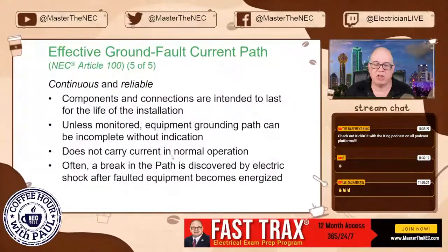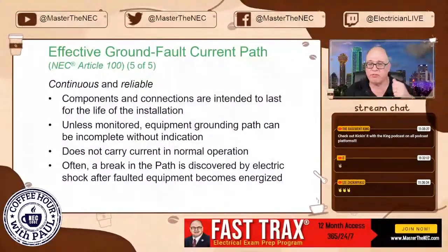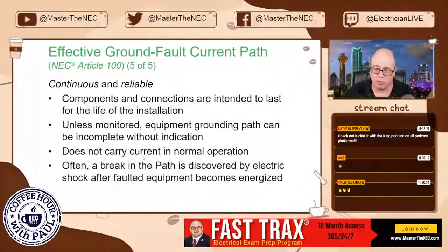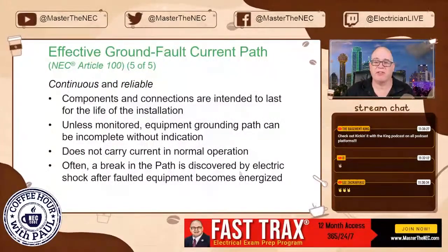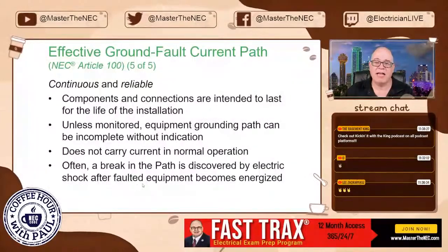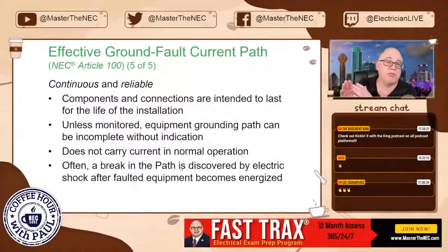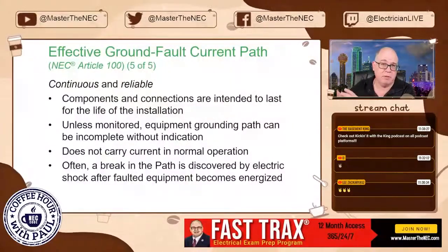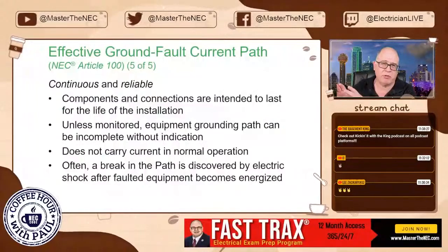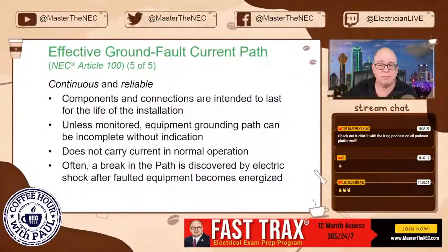Does not carry current normally. Exactly right. Equipment grounding conductors and all the raceways are not designed to carry current under normal conditions. Okay. Often a break in the path is discovered by electric shock after faulted equipment becomes energized. An improper neutral to case connection downstream, whereas you take a remote distribution panel and you accidentally connect the neutral to the case like you're not supposed to.